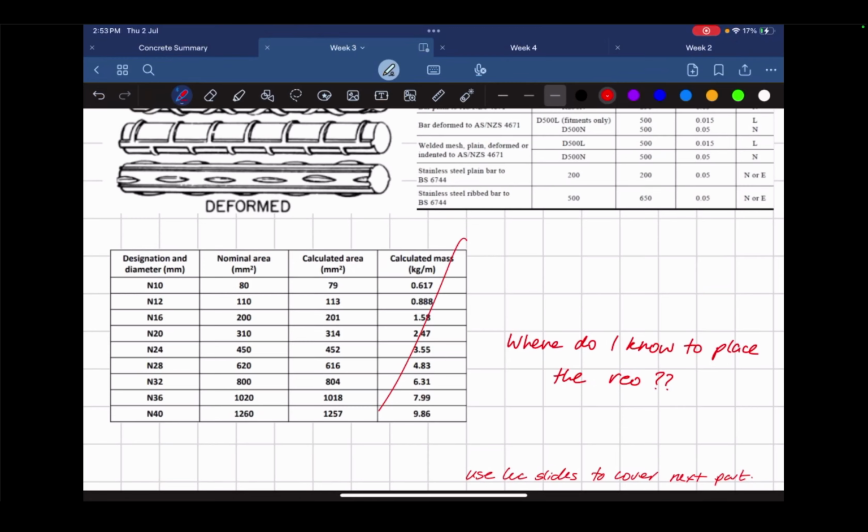But if you were to look at a microscopic level, imagine these are fibers. Pretty much what happens is these fibers at the top are going to squish into each other, which means it's in compression. The top fibers are in compression. The bottom fibers here